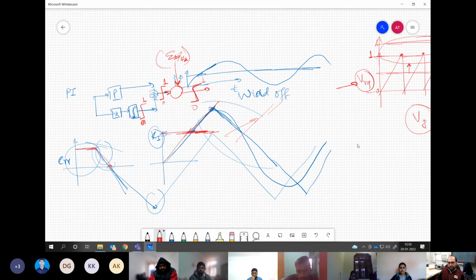In effect, you cannot have anything fed more than 1 to this comparison. You are losing the control. You may avoid the saturation limit on the output, but you certainly need some internal clamping for the integrator.